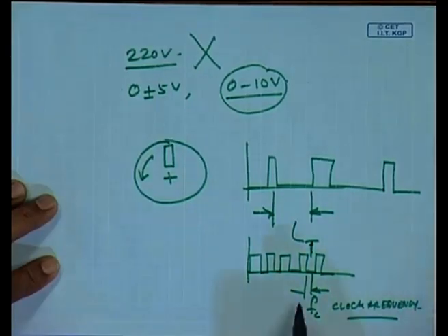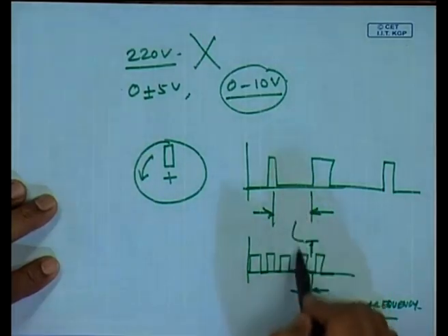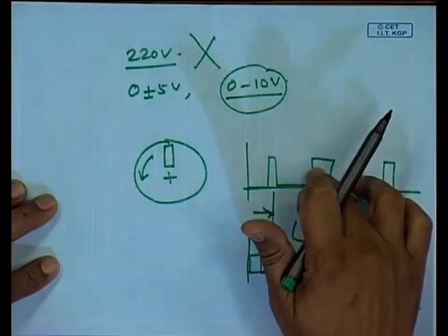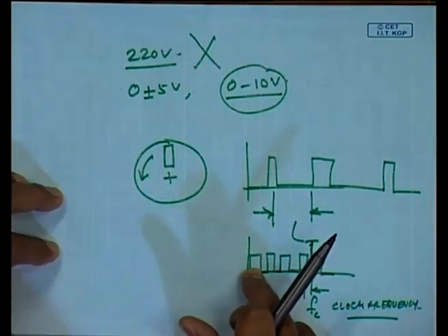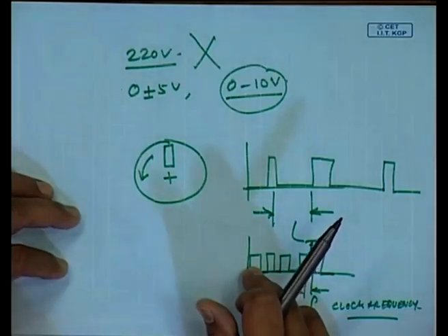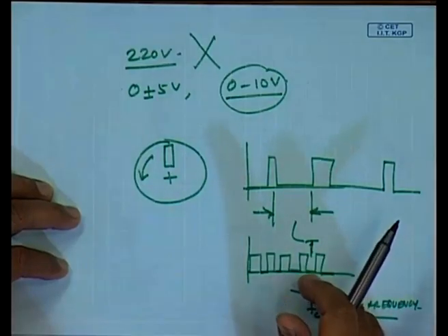So, I can compare this clock rate with the pulse actually measured, and then say relative to this clock, what is this guy's speed. So, this clock is given by an A to D card, which has a counter or a timer, okay. And these are very high frequency clocks. When we talk about measuring using rotary encoders to capture phenomena from mechanical machines, I will go into details on this then.